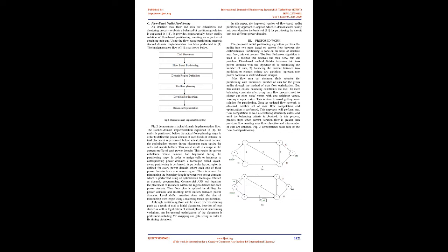Different types of netlist partitioning have been studied in the previous literature. We highlight 3 basic netlist partitioning approaches. A. Move-based netlist partitioning. Kernighan and Lin [6] and Fiduccia and Mattheyses [4] proposed move-based algorithms for network partitions. The algorithm in [4] iteratively moves or swaps a pair of vertices, but in [6] in any single move only a single vertex will be moved across the cut at reducing net cut costs.